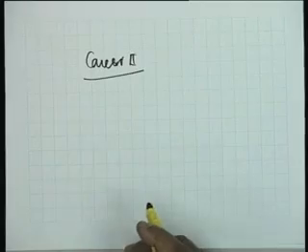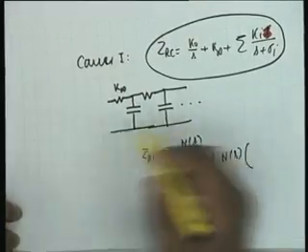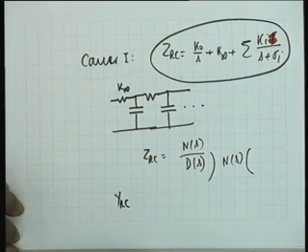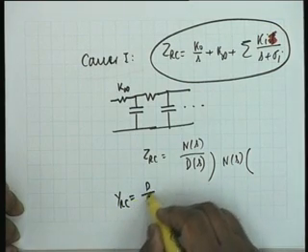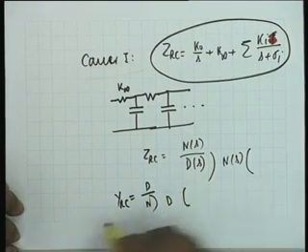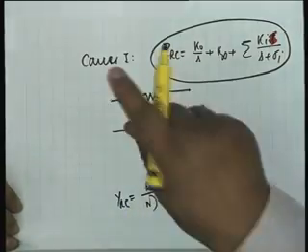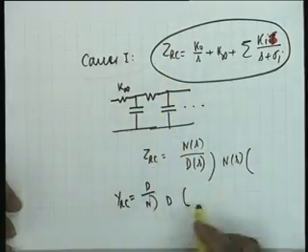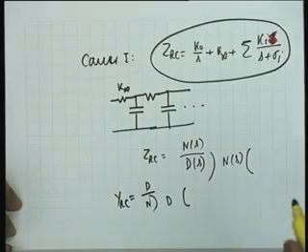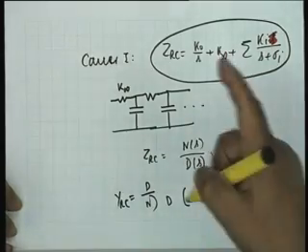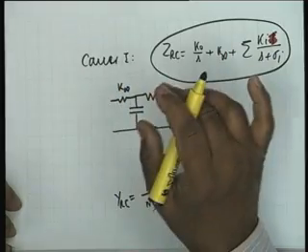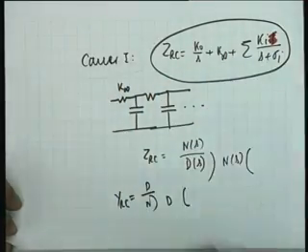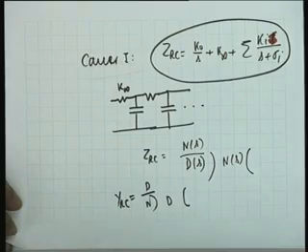Question is, suppose we invert this, YRC is d by n. Can I do a continued fraction expansion starting with the highest powers with YRC? No. What would that mean? It would mean removing the constant value at infinity from YRC, which you cannot do, right. What we can remove from YRC is its DC value, not the infinite frequency value. Okay.